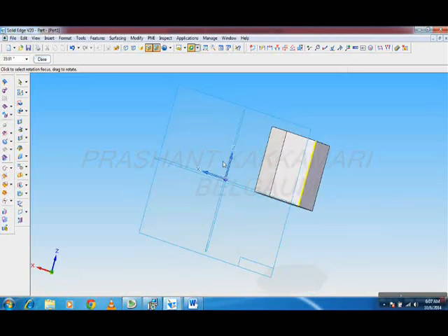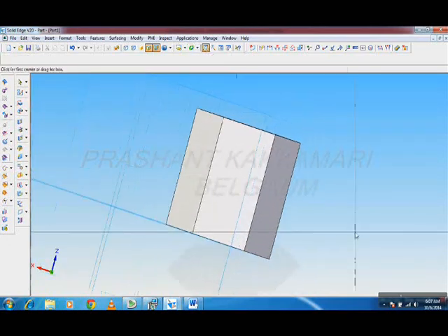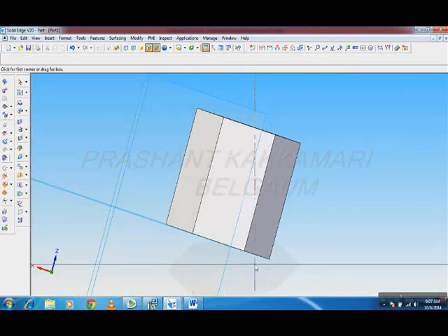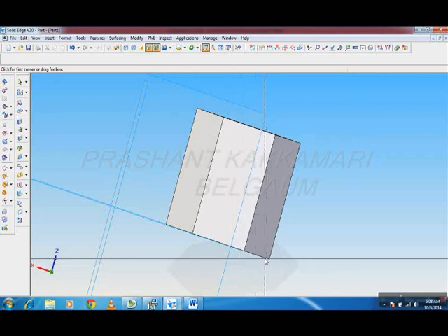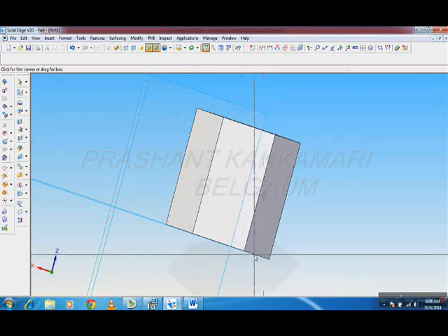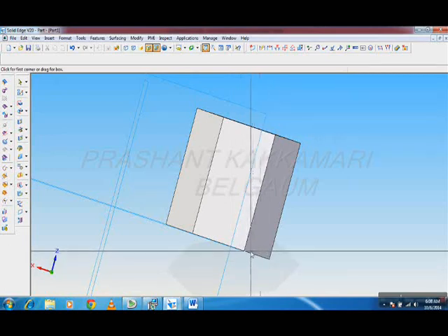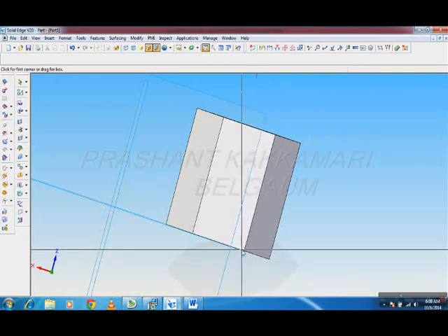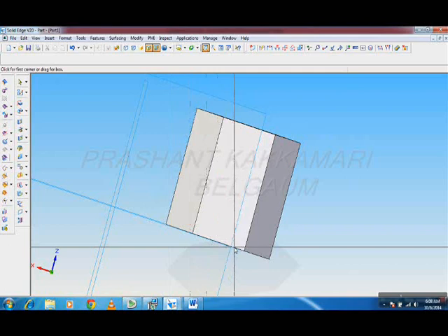So like this it will be inclined. Is that clear? So now, when it is inclined, A is here, and observe all the edges, A to B and A to F. A to B is behind, A to F is in front. So these edges or complete face is equally inclined to HP. So that aim you are going to achieve.